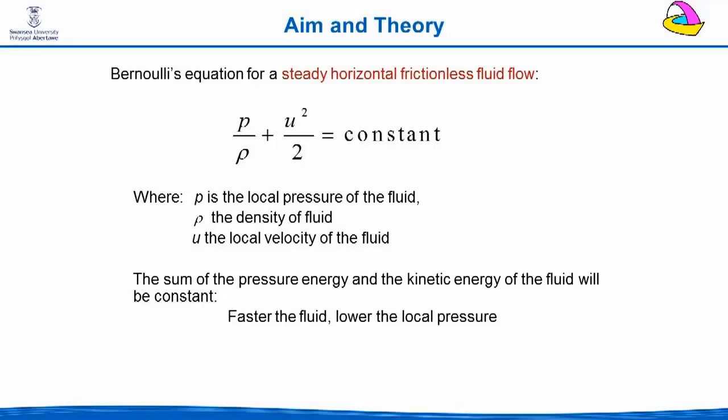The aim of this experiment is to verify Bernoulli's principle. This is an important law of fluid dynamics that states that for horizontal, frictionless fluid flow, the sum of the pressure energy and the kinetic energy is a constant. This therefore gives us a relationship between the velocity u and the static pressure P, such that if we increase the fluid velocity, the pressure must decrease to satisfy this expression being constant.